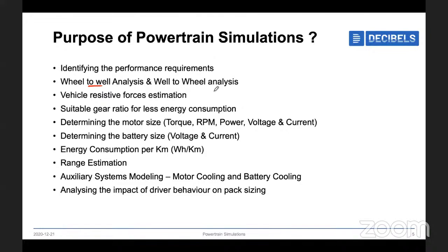But the other way around, they will tell you that whatever motor you choose is up to you, but come up with these kinds of performance requirements. From that point of view, these powertrain simulations will help you a lot. With the outcomes of determining the motor size, you can select your own motor and go for building the vehicle. And finally, we can size your battery pack in terms of voltage, current, energy, C rates, and mass.